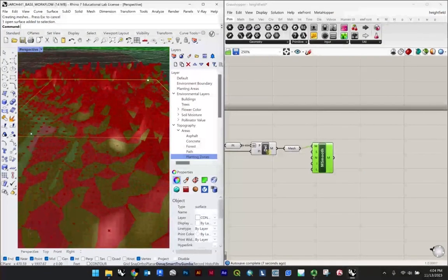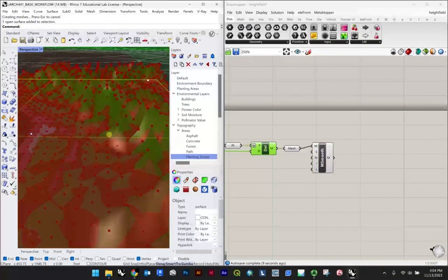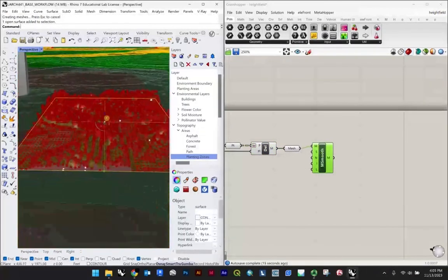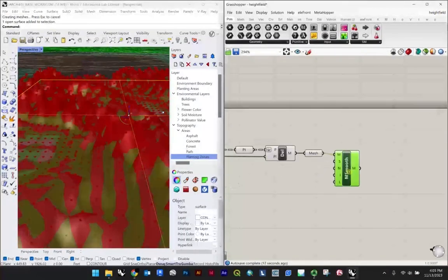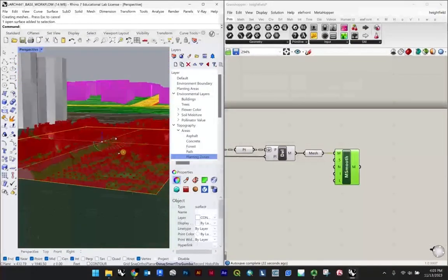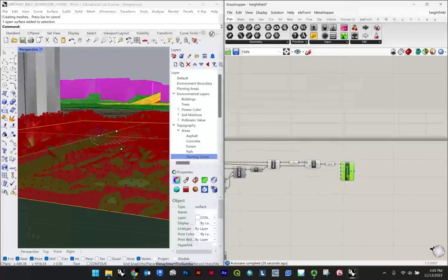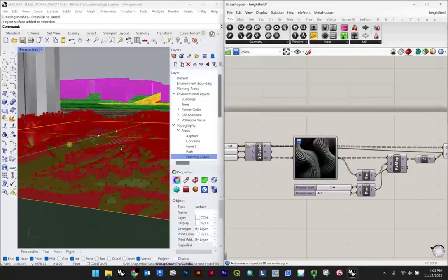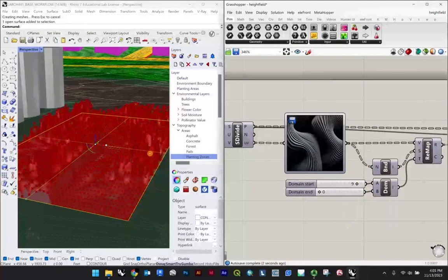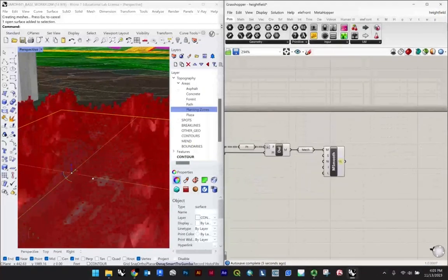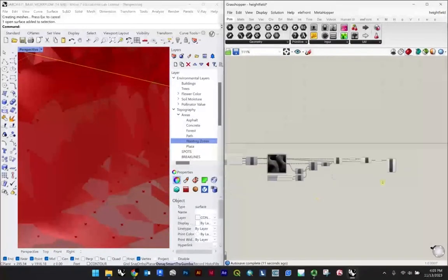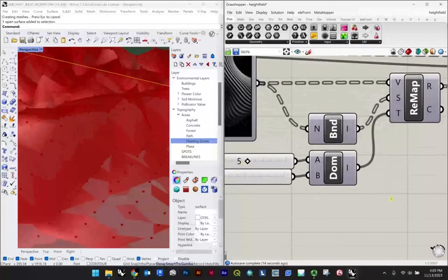You can see here how in the Delaunay mesh, which when I click on it is in green, you have these spikes. And our smoothed one is a little bit more rounded off, right? So you have those high and low points still, but it's a little bit more balanced in terms of their relationship to one another. When we're talking about landform, this is important because it's a little bit more believable and buildable. We can, of course, play around with this by starting to up our domain. And let's go back. So these are pretty steep walls. I may go back and lower this a little bit.